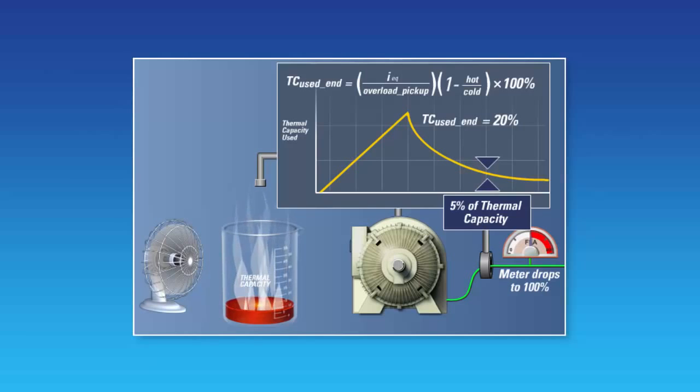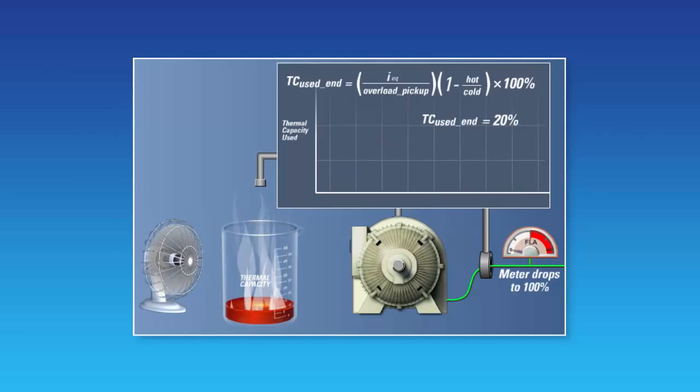Stopped cooling time. Note that for the GE Multilin 369 and 469 relays, the values of the running and stopped cooling times which are to be entered into these relays must be 1/5 of the actual stopped and running cool times.